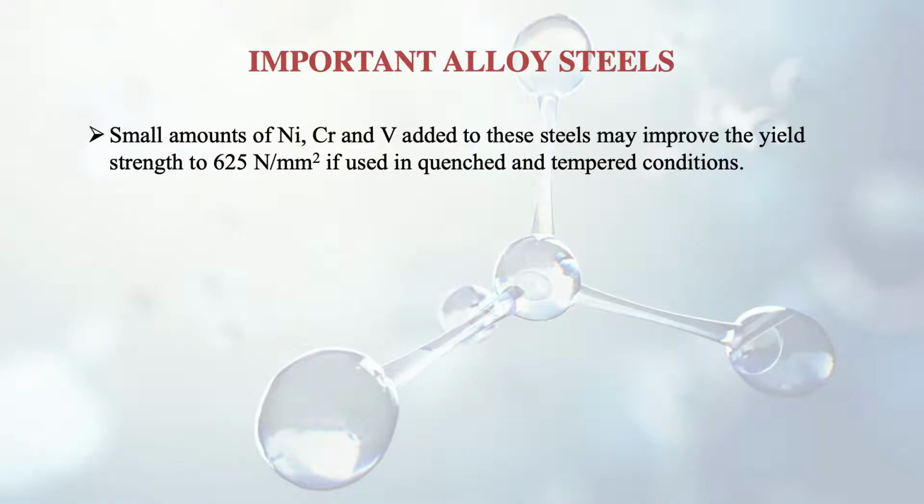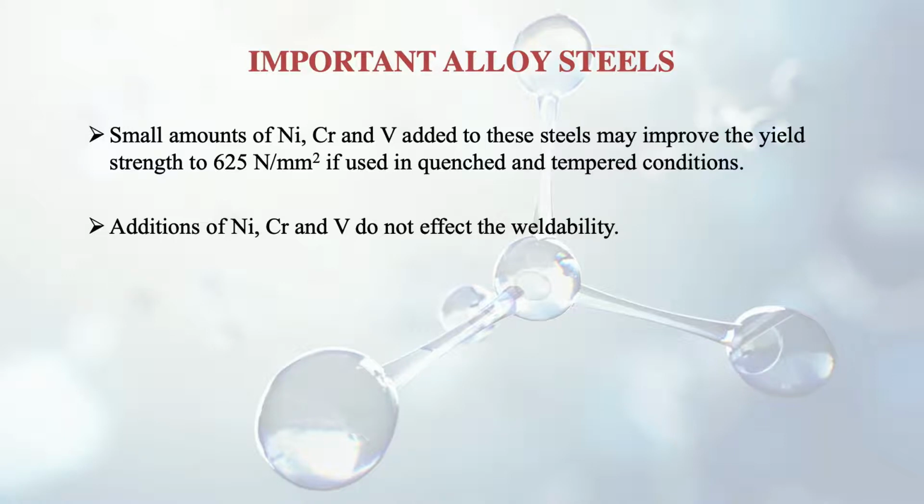So you can see how much the yield strength has gone higher if used in quenched and tempered conditions. This is the case when it is used in quenched and tempered conditions. And furthermore, additions of nickel, chromium and vanadium do not affect the weldability.